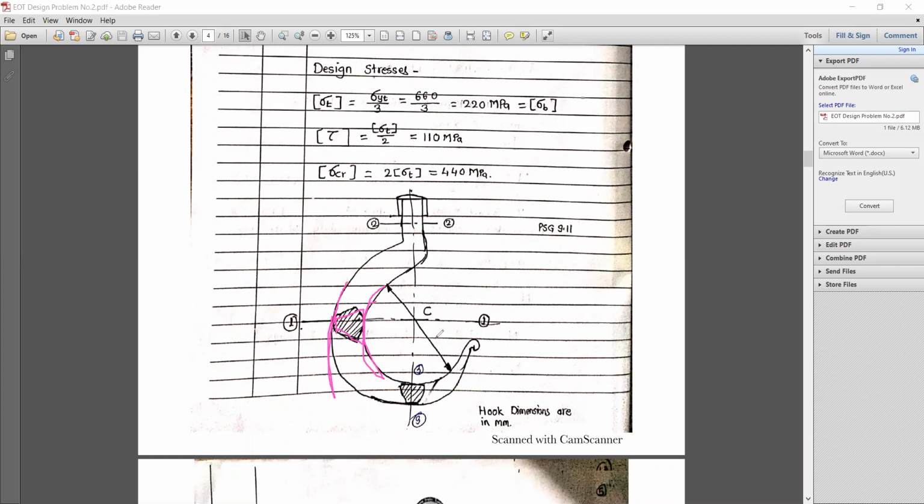We can go for a square section also, but it increases the weight. A rectangle similarly increases the weight. As the inner fiber carries a heavy load, its thickness should be high, and the outer fiber carries purely compressive loads, so its thickness should be as minimum as possible, so that both the weight and strength criteria can be satisfied properly. Okay, so let's see the design.